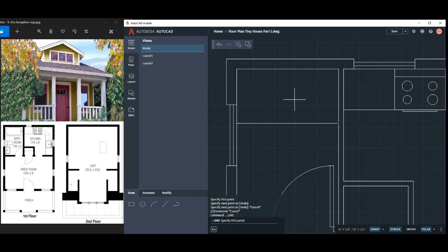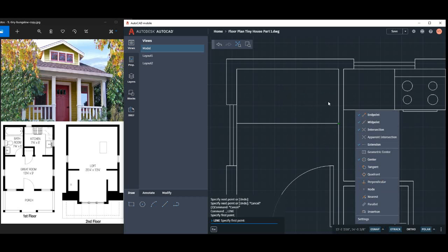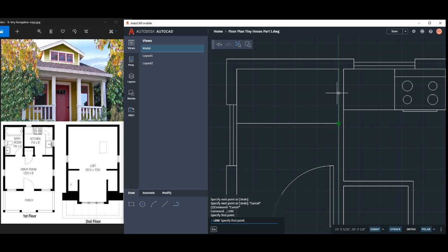So what I want to do here is find the center of this tub to find some points that I'm going to start creating the midpoints of the rectangle on. Just going to turn on midpoint here, and grab my line tool. And I'm going to find the midpoint, shoot it across. The reason I did that is I need to center this rectangle within that inner shape that I'm creating. So I just found the center of these 2 points here.